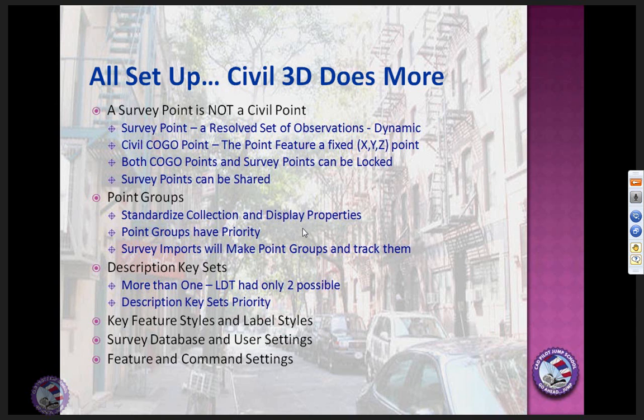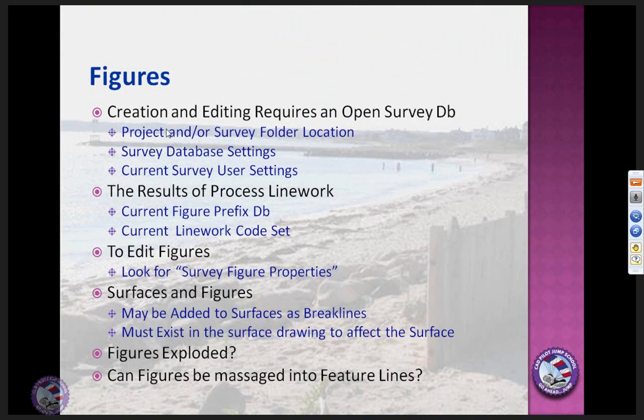Remember the point groups we already talked about. A couple of key things. The creation of figures and editing requires an open survey database. If you're just putting them in a drawing, you can open the database read-only and pull the figures you have created out of that database, backup or whatever it came from, into any drawing you want, directly from the survey database. So if you make the survey database accessible to other users, getting to the primary figures to do that kind of thing is a useful device.